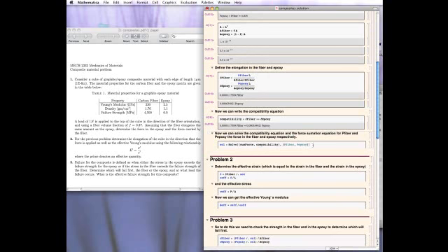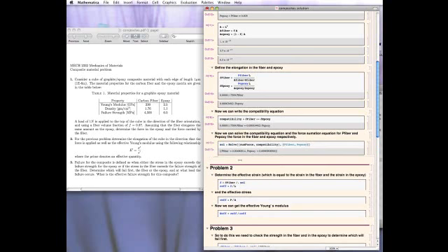In Mathematica, you can do this by hand if you want, but again, Mathematica has this Solve function. Here it's solving these two equations for these two unknowns, and it's giving a name to the solution, just calling it solve. So here's the solution. It says the load in the fiber should be 0.0049, and the load in the epoxy should be 0.0000908566. Those values are stored in the solution. So that's the answer to problem 1.